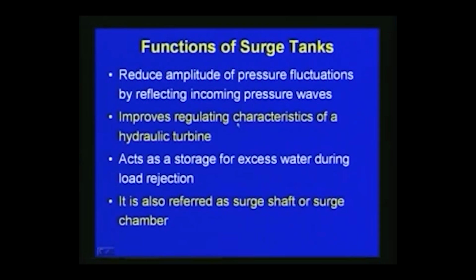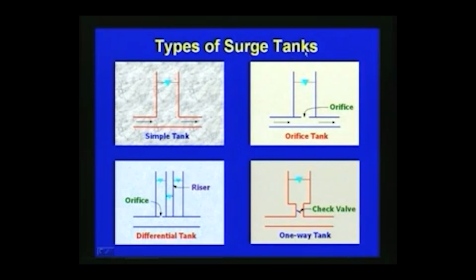So it improves the regulating characteristics of the hydraulic turbine, and it also acts as a storage for excess water during load rejection. It is also referred to as a surge shaft or sometimes a surge chamber, depending upon which way we deal with it. There are different types of surge tanks.